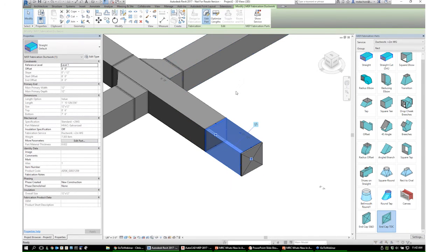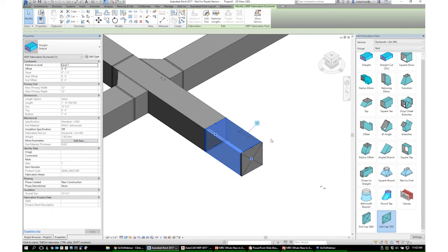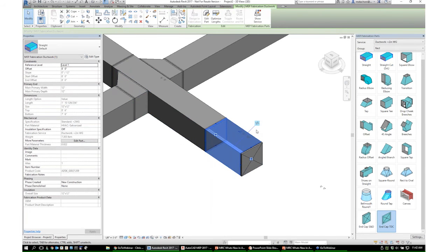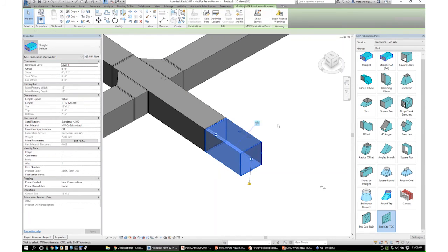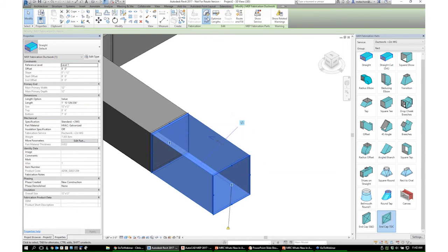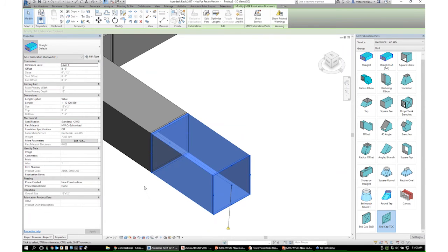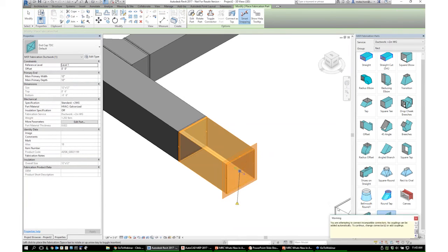And when I look at this part right here, under connectors, what should happen is it should give me a warning that I've added a TDC connector to the end of a slip and drive duct. But what I can do with this is, if I select the duct, let me go ahead and get rid of this guy right now. I can look at the part again, edit this part, and go to connectors, and you'll see that the end part right here, I can modify this, and I'll pull this down and make this, say, a TDC connection like that. So there's my TDC connection there. Add in my TDC endpoint.